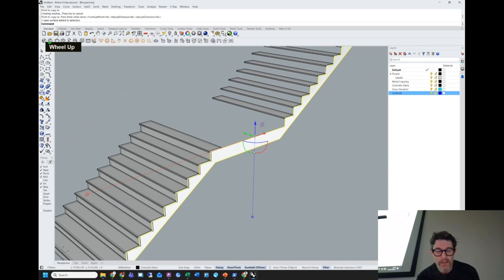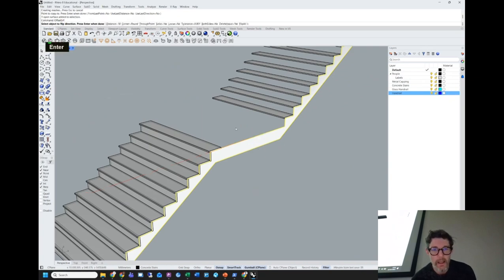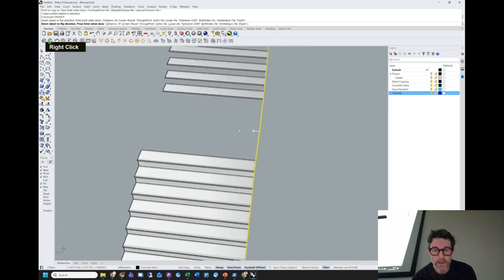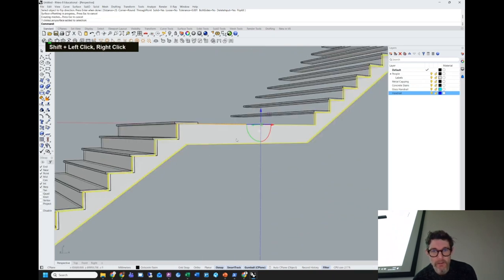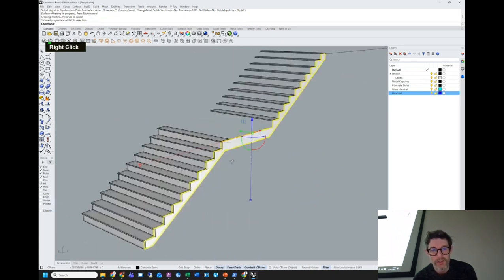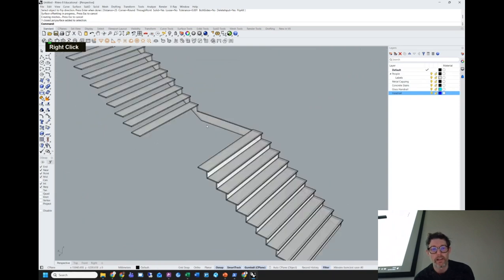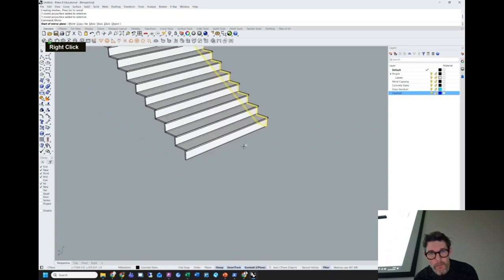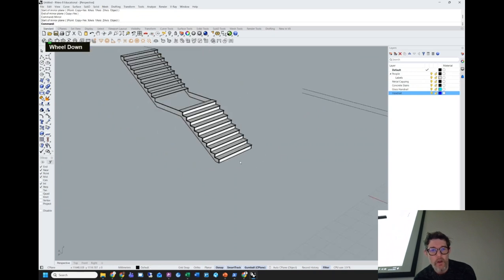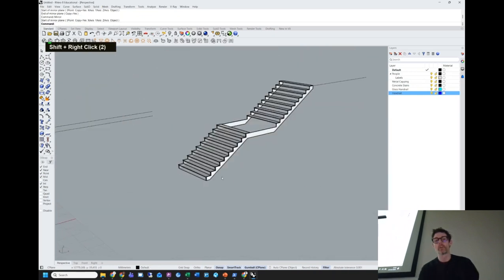Usually, these stringers sit on the edge, and I can offset that, and I'll go in that direction, please, and I'll make it, I don't know, 25 or something. And now what's going to happen is that piece of wood is then going to support these other bits of wood. So we clearly need 2 of them. I'm going to mirror that from the middle. And if I have my mid snap turned on, I can find the middle of any line very quickly. I can mirror it there. And now I've got one on both sides. So now I've got the beginnings of that timber staircase.